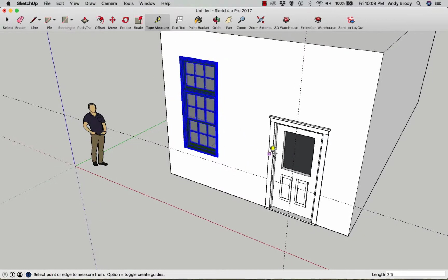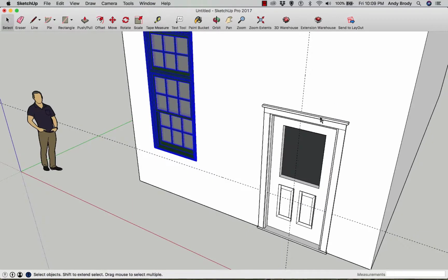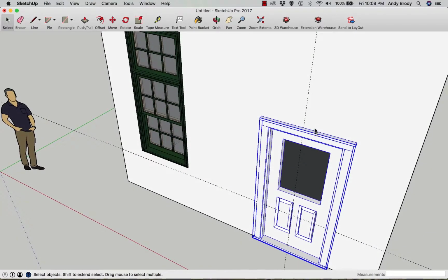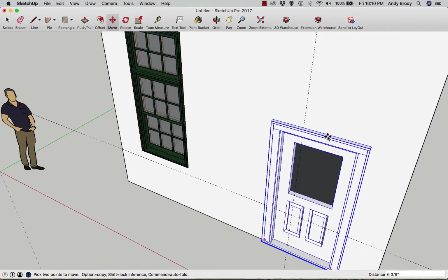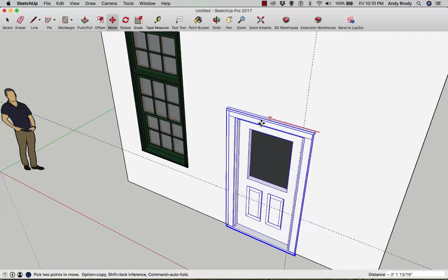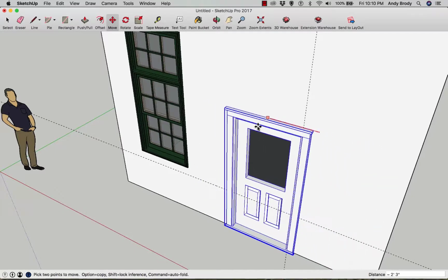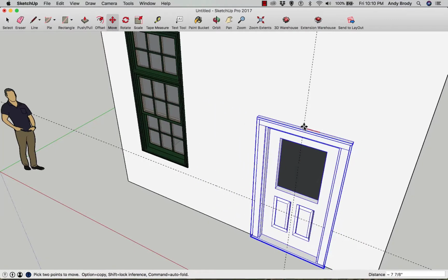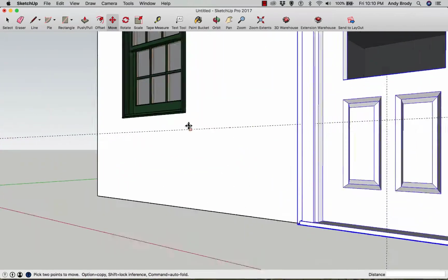And then I'll show you a little trick for moving the window that I didn't talk about in the book. So when moving these objects, again, you're going to want to make use of the reference lines, but also the geometric snapping points, O-snaps in AutoCAD speak. So I'm going to use the midpoint in this component. I want to force it to stay in the red direction to lock that inference because I've already placed this door on the ground. And then it's a matter of dragging my mouse over the reference line that I drew. Okay. With these windows, the same thing.